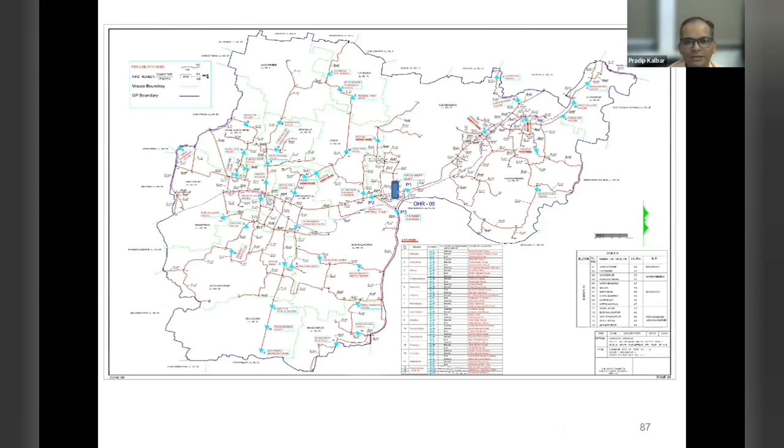This is not magic, right? It cannot go like this. We have to plan for this. So decentralized infrastructure: instead of 9 lakh liter, if they had constructed 3 tanks of 3 lakh liter capacity, this situation might have been avoided. So when we monitored, only this area was getting water. The rest of the people were managing somehow with other sources. So even if the Ganga river was there, they were not getting water, that's the irony of our situation.